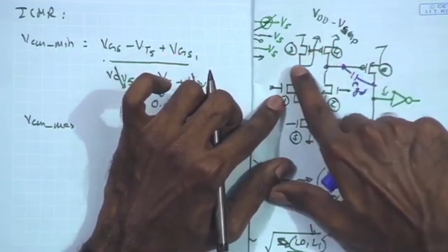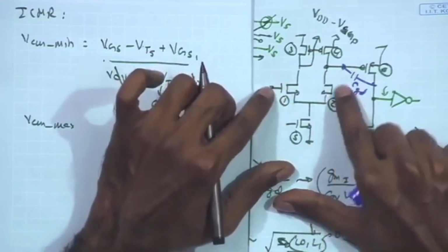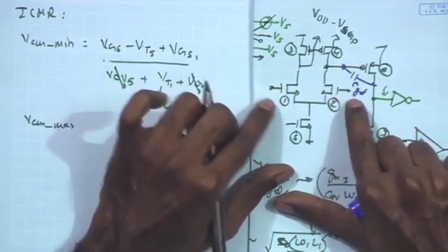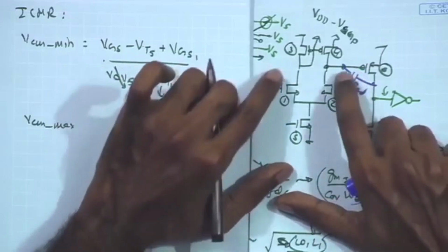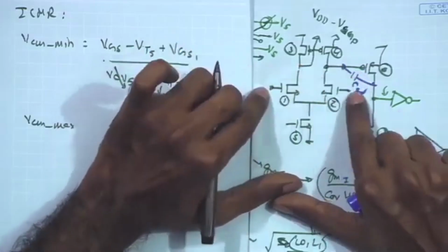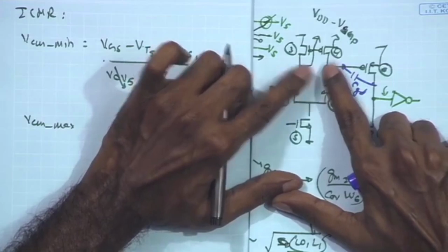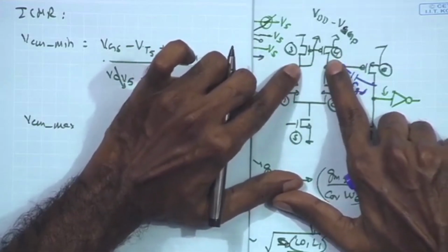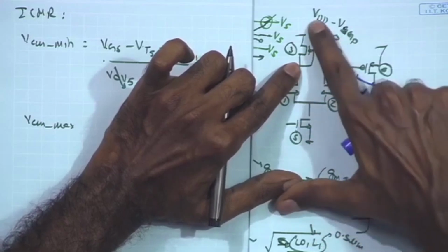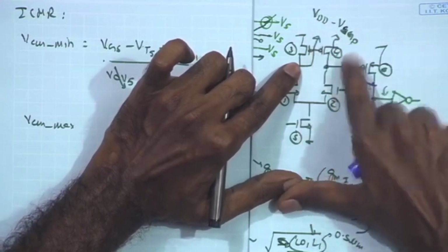So, this potential is VDD minus VSGP, and remember for this differential amplifier with current mirror load, if you are increasing this input gate potential, if I assume that both of them are close together, the output potential over here will be close to the diode connected voltage over here, close to the required value VDD minus VSG.